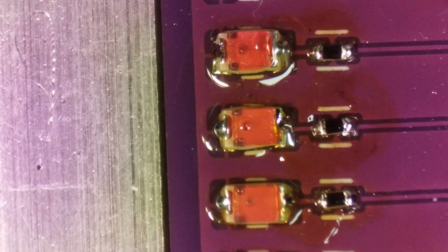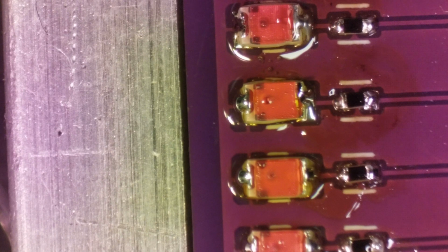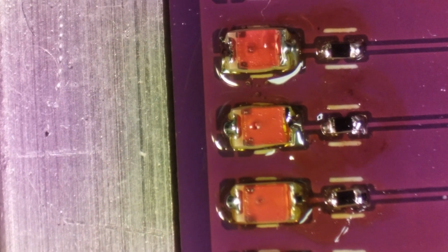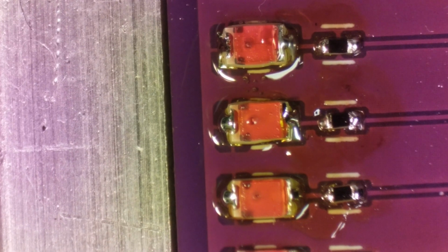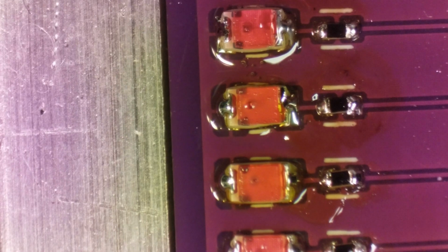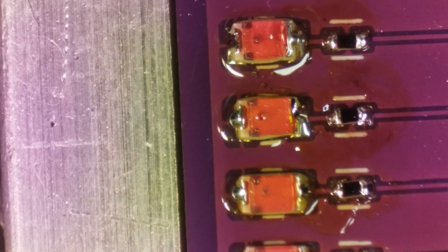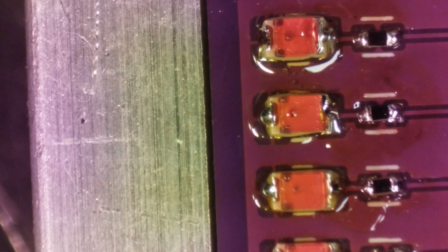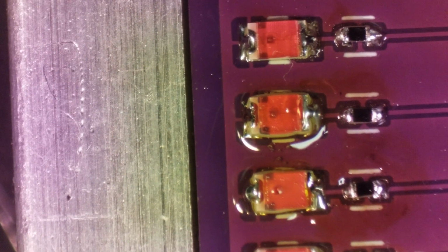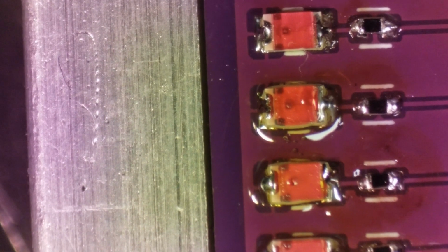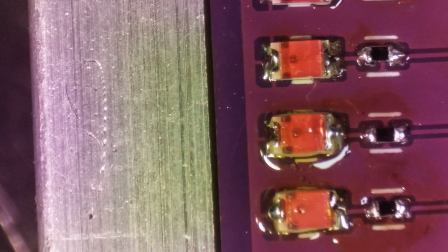The reason IPC doesn't like to have this much solder on it is because when you have the solder bumped up on the ends like this, over time through changes of temperature, that ball of solder on the end can pull unevenly on that chip resistor or any part, and it can cause it to crack under high changes in temperature. None of this we should have to worry about here. But when you get like 1,000 boards out in the field and they're going through whatever the customer puts them through, which you don't really know, then it can cause failures.